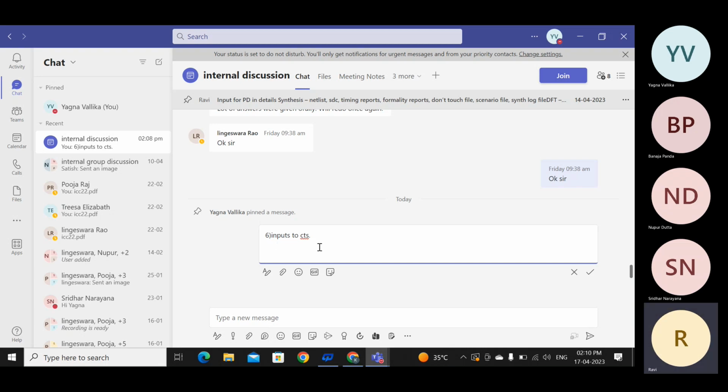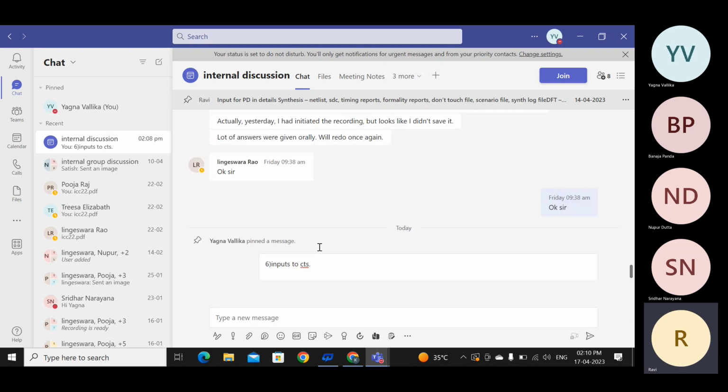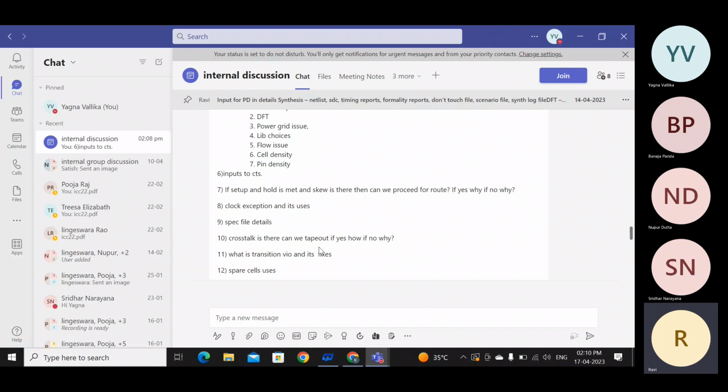The other thing is, you have to give the proper metal layers to route for the clock tree. Try to use higher metal layers for the major clock construction, and provide double spacing single width as a start, sorry, double spacing single width. But if there is enough route available, and because double width would also mean that a lot of latency and buffer levels are getting added, so don't over constrain by adding 5 picoseconds skew, etc. Be realistic, so you have to do some trials.